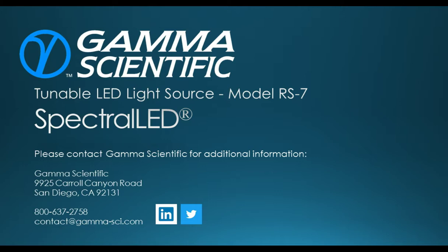So we're relating the wavelength to the drive current because regardless of our temperature control, the die junction is still going to have some small temperature change. And so driving an LED with 10 milliamps of current versus driving it with 1 amp of current, even though the substrate is under very, very tight and accurate thermal control, there's still a difference in the peak wavelength, the nominal peak wavelength.